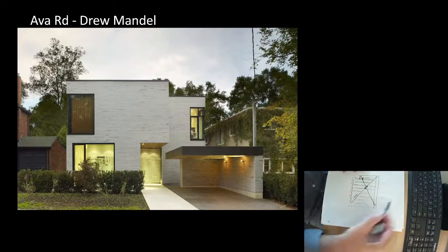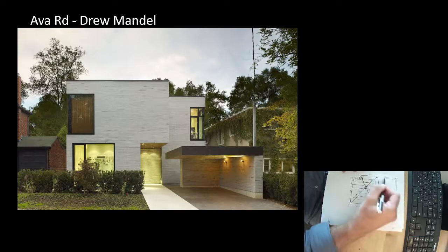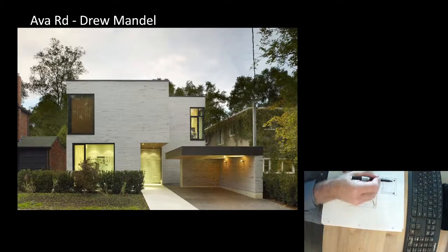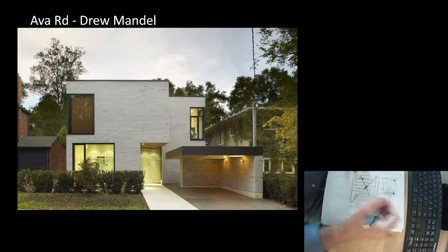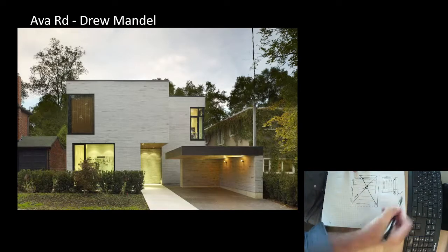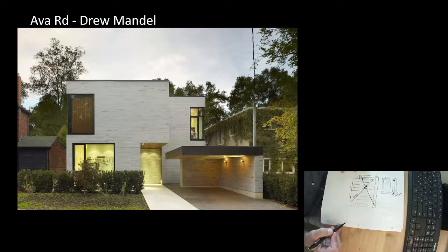It certainly is not. Certainly Shannon could have put a beam here, cantilevered it out of the wall, put another one here, cantilevered it out of the wall, and infilled with wood this way. That would have been just fine, but we've got this big bending moment that we have to transfer into the wall right here, and that would be a real challenge. So other ways to do this.